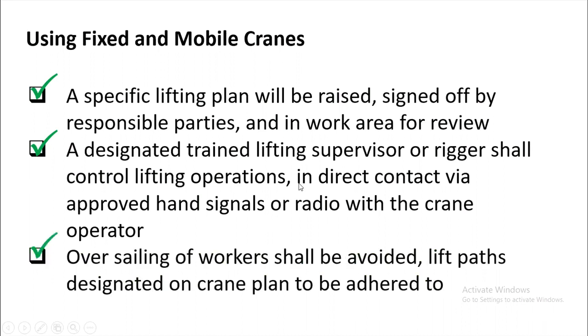Oversailing of workers shall be avoided. The lift path designated on the crane is to be adhered to. So this is the one I taught already. When you are planning lifting operations or fixing a crane, you need to identify those workers below your lifting direction, so that you can eliminate the presence of workers in those locations.